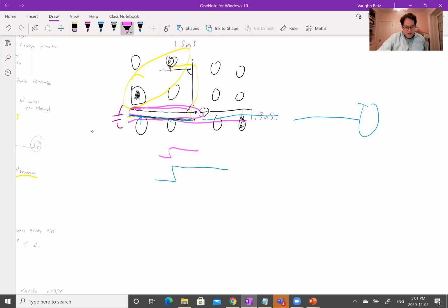So that means if it was about to send out a rising edge, that edge is actually going to be extra fast. The delay of this wire that I've circled here is going to be reduced if the blue wire is transitioning in the same direction at the same time. If they're going in opposite directions, so let's say the blue wire right at the rising edge of the clock is actually discharging, that's actually going to slow down what happens on the clock. So now the clock's going to be delayed. So this difference between them is jitter.